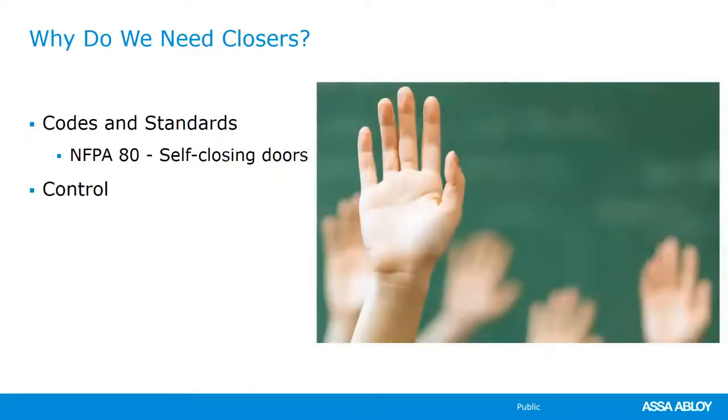If you're putting door closers on a school, for instance, and you have these high traffic doors that you want to close to protect the students in the school, maybe it's an exterior door and kids are leaving. If you've got a door that is just slamming, maybe the door closer is out of adjustment, maybe it's leaking, maybe it was hung on spring hinges, which again, I don't recommend, we need the door closer to control that weight, that inertia, so that we don't smack it into a wall, that we don't damage the hardware itself, damage the door frame, damage the door itself. Doors are welded, frames are welded oftentimes, and a slamming door can actually wreck everything in that.